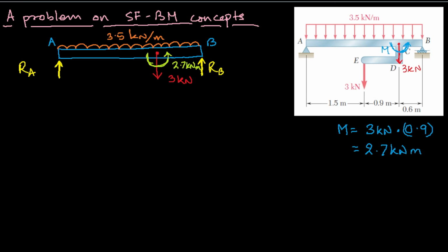Okay, so then what we should do is next step, as we always do, we should look for force, area, or material discontinuity. Okay, now if you see this, there is only one kind of discontinuity, that is the force discontinuity at the point C. Okay, so this point is C. And that's how we are splitting this full beam into two segments. Okay, now segment by segment we will try to evaluate.